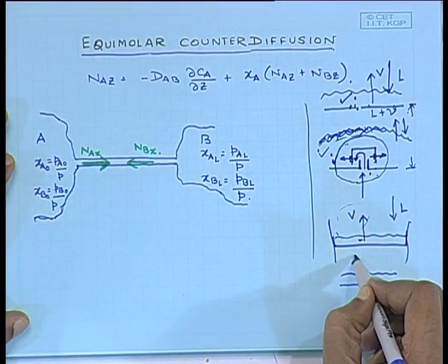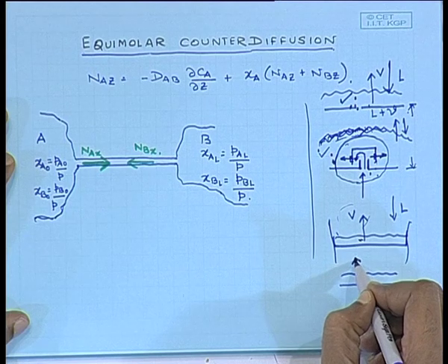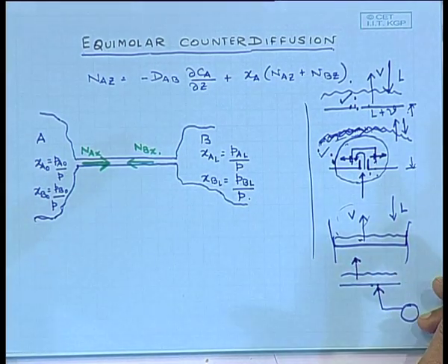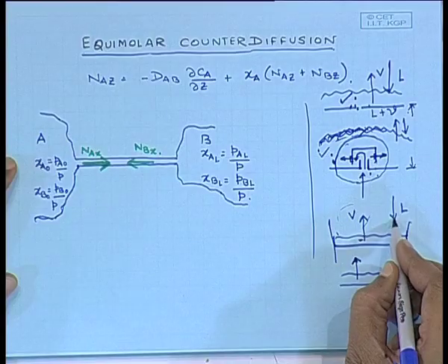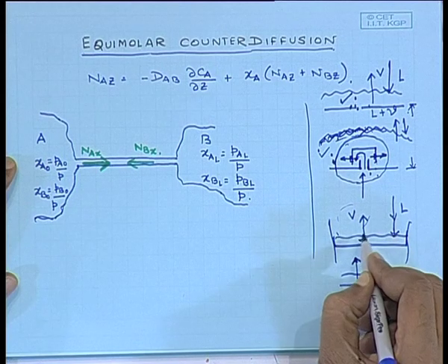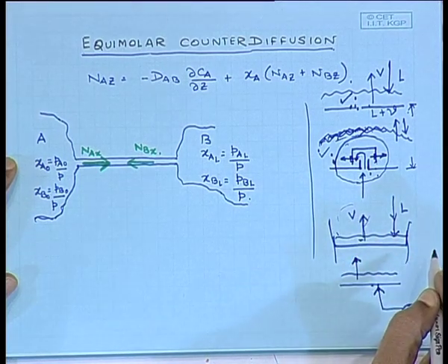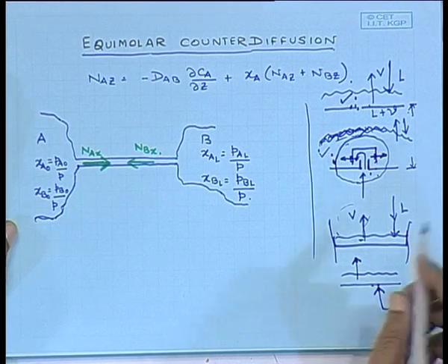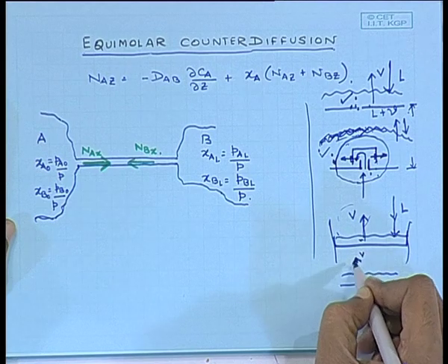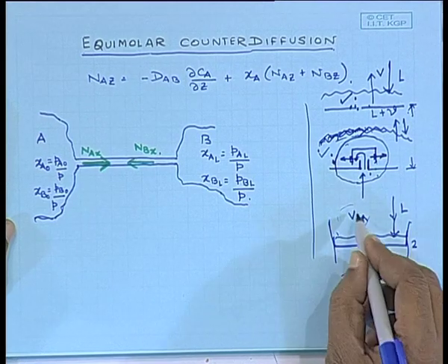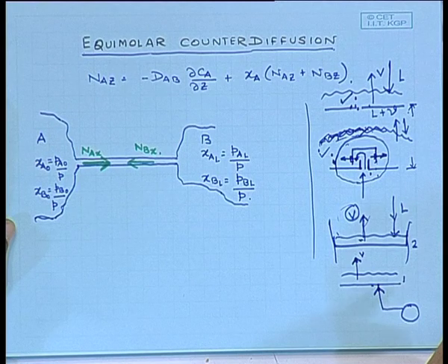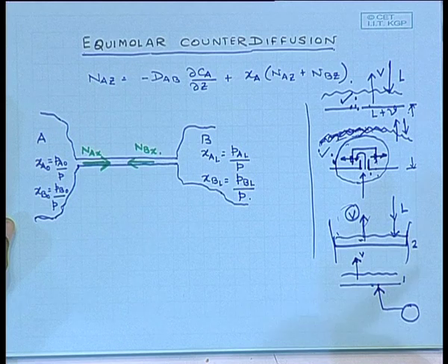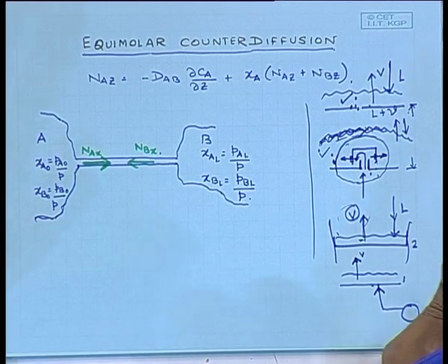So, for each mole of vapor condensed, how much vapor are you creating? Or rather, each mole of liquid coming over here, how much vapor are you generating? Would it be the same amount? Each mole of vapor which is coming from tray 1 to tray 2, how much vapor are you going to generate? 1 mole or less than 1 mole or more than 1 mole? Why less than 1 mole? There is no loss. Let us assume that there is no loss.